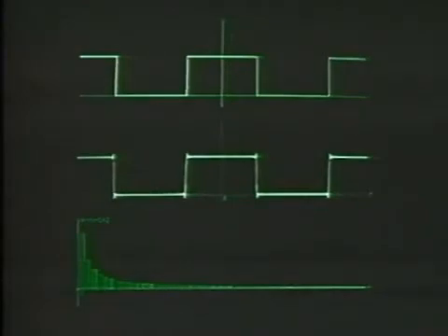Now, the energy in the error asymptotically will approach 0, although point by point, the Fourier series will never be equal to the square wave. It will at every instant of time, except at the discontinuities, where there will always be some ripple corresponding to what's referred to as the Gibbs phenomenon.